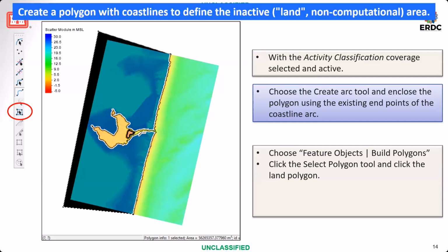However, wetting and drying over the tidal cycle might enable water to reach that area, that elevation. So you might want to check to make sure that area is not inactive. If it's a full polygon, make sure you double click all the solid areas to make sure that none of the areas that you intend to be active have accidentally been set to inactive by default.